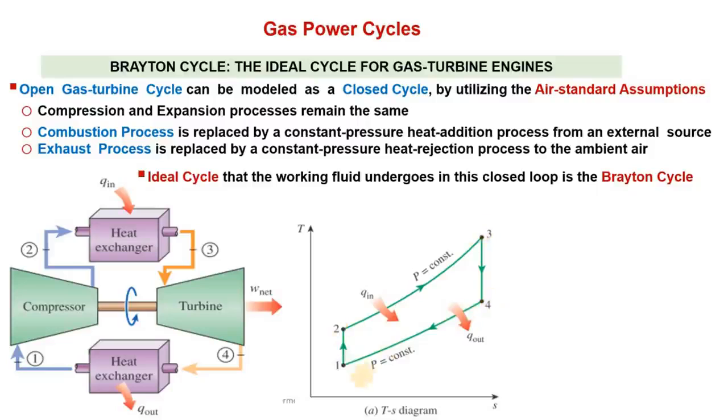So these are the pressure lines in gaseous region, right? Hopefully if you have a very clear idea how the pressure lines look in the gaseous region, then you can easily draw this TS diagram for gas power cycle, and how the pressure lines change their directions inside a dome. That's why the pressure line variations were quite different in case of steam turbines.